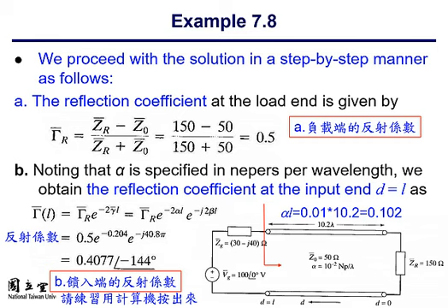In fact, it's minus J 4 times 10.2 pi, and every 2 pi it goes back to the original place. So you need to account for 0.8 pi, which is about minus 144 degrees. Okay? Be sure you understand how to come up with these numbers, right?